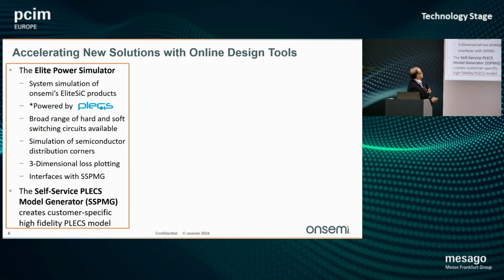And finally, I want to end with some tools that we have available online. So we have a very powerful simulator tool that's online. It's based off of Plexim, and it gives you a simulation of our released products that are in the market. What's really nice about this is that in addition to the typical performance that any model or simulator will give, our models also have the corners simulated as well. So you don't have to do an inverter simulation and guess via Monte Carlo what the worst case would be. This is already baked into the corner data that's being fed into the models here as well.